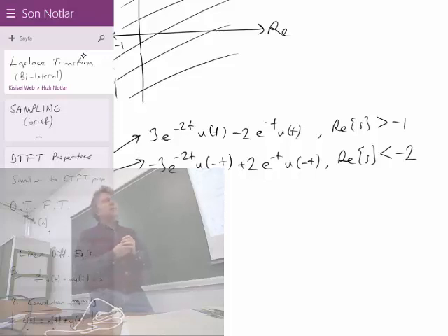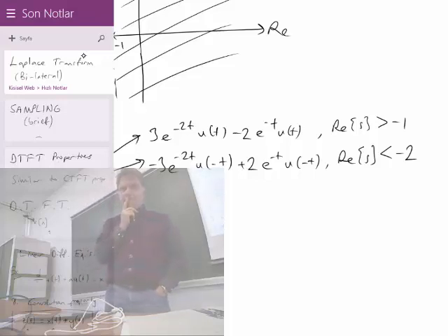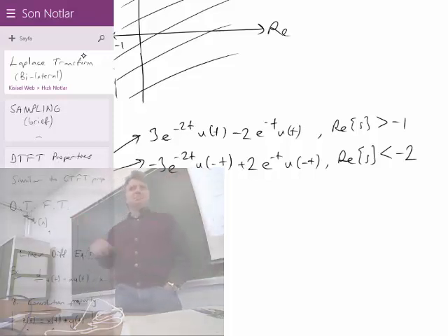They are not behaving nicely. How come the Laplace transform still exists? Why? How can we say that a transform of this ill-behaving signal still exists under certain circumstances? Nope. As t goes to minus infinity, e to the minus 2t grows. It blows to infinity.